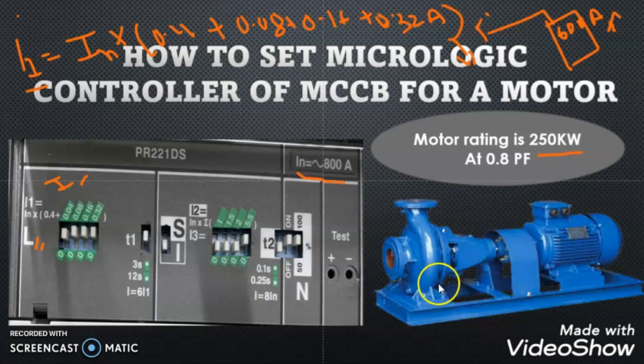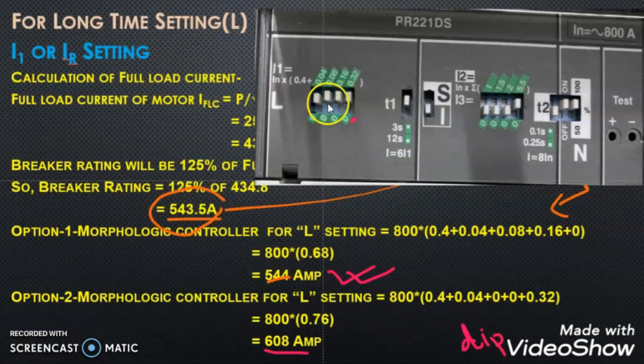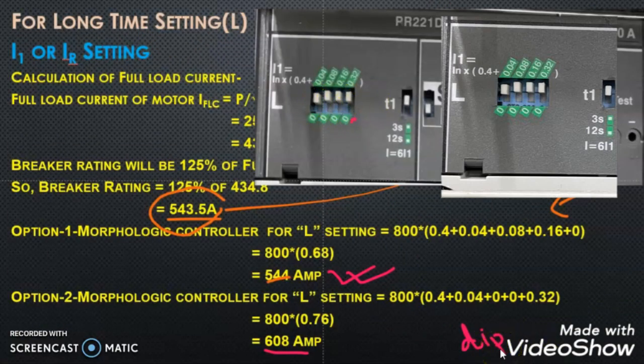So what is our intention? Our intention is to reduce this breaker rating as per our load requirement. These switches are called dip switches, DIP switch. By adjusting these dip switches, we can change the breaker rating. Let us take that we turn this dip switch which is at 0.32 to 0, then the breaker rating will be IN into 0.4 plus 0.04 plus 0.08 plus 0.16. 0.32 will be neglected as we put this dip switch down at 0 point.